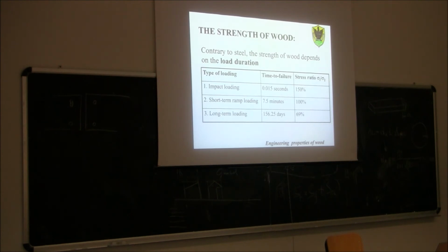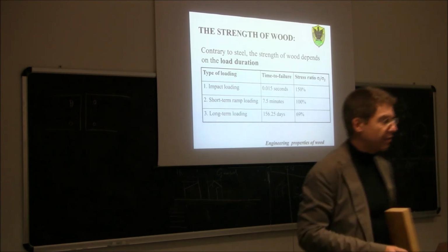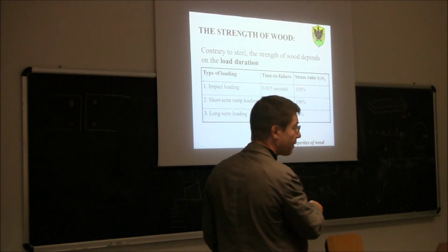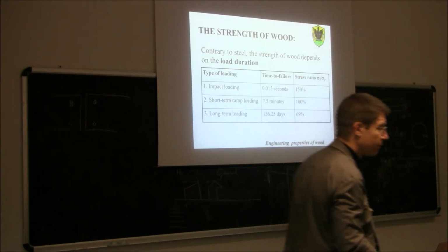This is what we call compressive strength, or tensile strength, and so on. Now, suppose that this ramp loading test, instead of being carried out over 7 minutes, was carried out in a fraction of a second, like this. So very fast. Would we get exactly the same strength as before? The answer is no. We will get higher strength, up to 50% more.